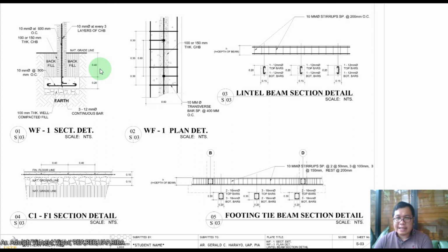Right now, class, what we use in my construction project is what you call the fast wall system. So we use what we call the precast panels, which has a thickness of around 0.075 meters or 75 mm. So it's just one whole system. Okay, so let me show you a video on what I'm talking about so that you can visualize it.